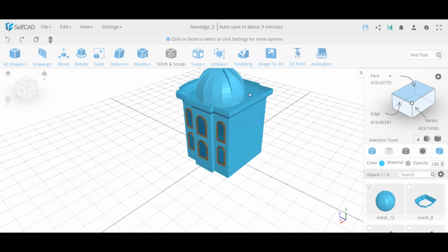So this is very important if you model for SelfCAD, which puts a lot of emphasis on 3D printing. If you model in most traditional modeling applications, not to say names, the ones you use for architectural design, it's almost guaranteed you end up with non-manifold geometry, and it's not usable for printing. You'll have to use Meshmixer or other tools. In SelfCAD, we initially designed this for 3D printing, so we put a lot of emphasis on manifold geometry. You have all of these tools to do it, and if you don't care about 3D printing, maybe you could just turn off the backface culling. But if you do care, if you want to print a model, this should give you that option.